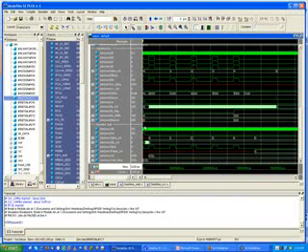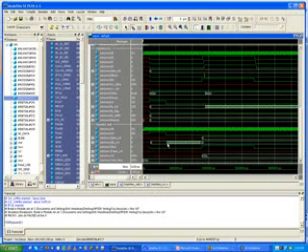Okay. Now we can zoom in on a little bit of this right here at the beginning. These are the actual sync bits. Remember I talked about the 5 sync bits? So here you can see, let's look in the transmitter. Right here before the first sync bit, you'll actually see, okay, there's the reset. And then after the reset finishes, this delay count starts counting, and it gets up to a certain value.